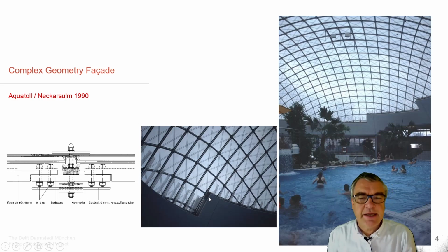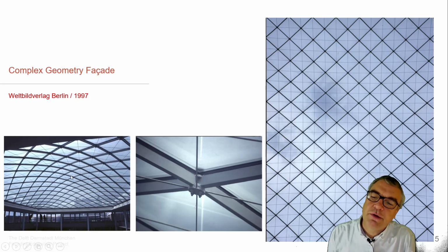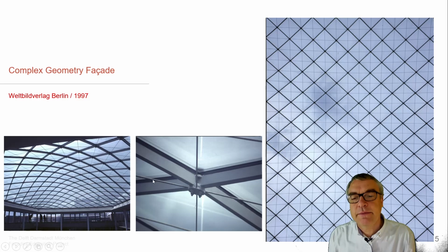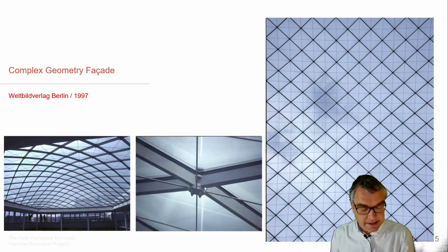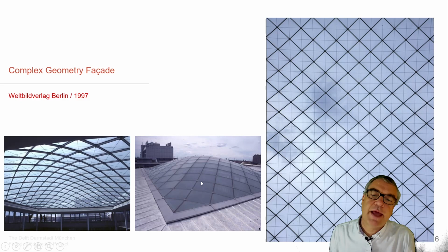It's nicely designed here by wrapping it with an inner and outer layer so that you don't really see the connection, how it is done. Next one, anticlastic curvature, so same orientation of radii in here, and then contradiction of the radii at this area. Same cable grid system, so the main bars with the pre-stressed glass, and then the outer surface, as you can see, this is the typical shell with a synclastic curvature, and this is the edges with an anticlastic curvature.